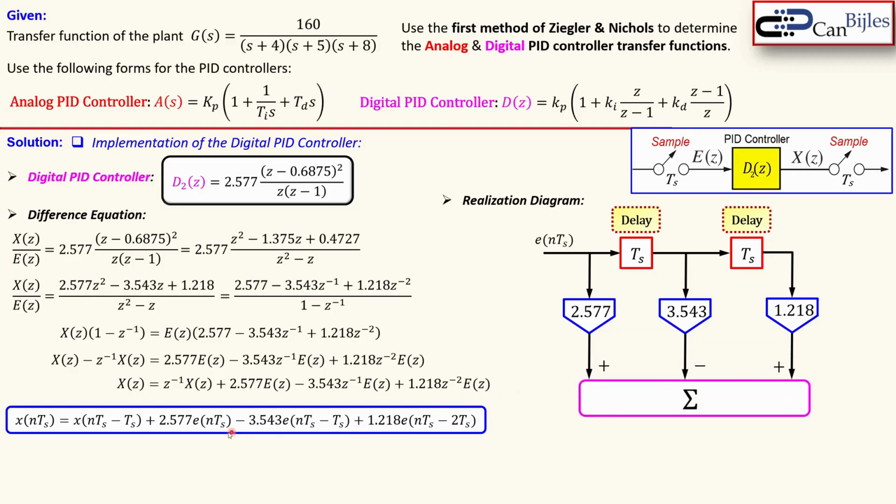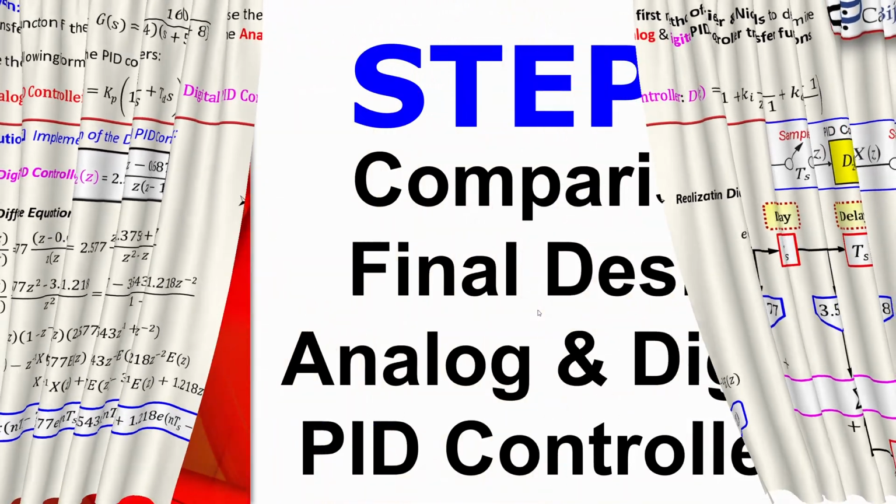Well, it's not the full story, because we have also this one, which is the X, the 1 delayed version of the output. So we have the output, but that also needs to be delayed 1 sample period, and then added to this block, and then together that will create this output. That's how you generate this discrete or difference equation into this realization diagram. Okay, now that's for that.